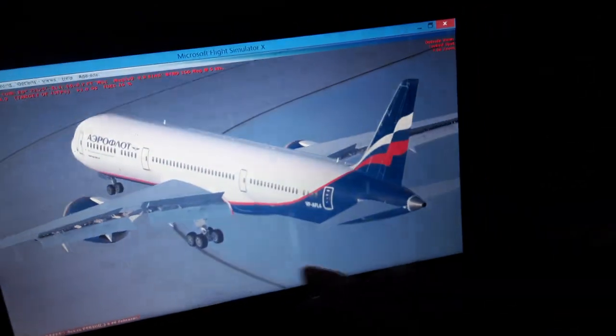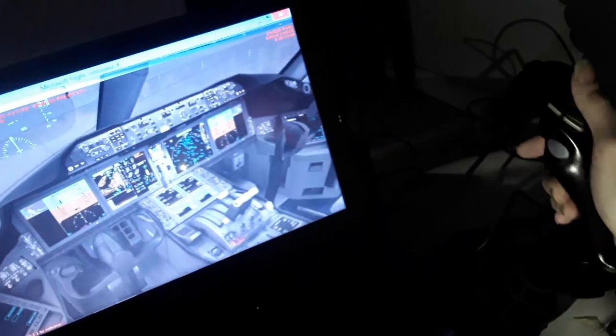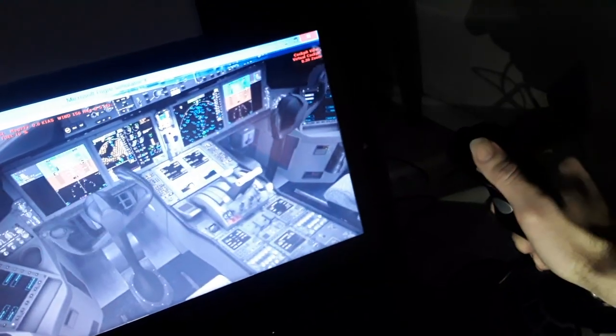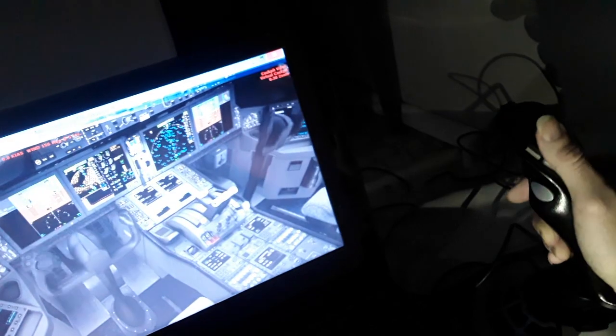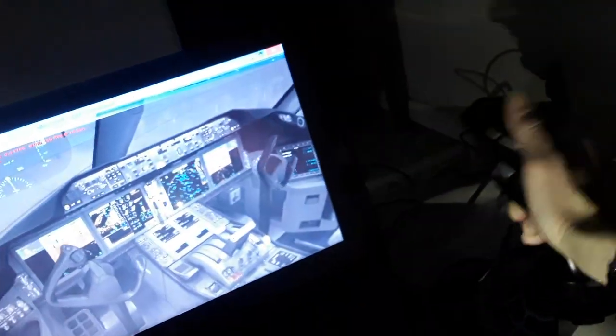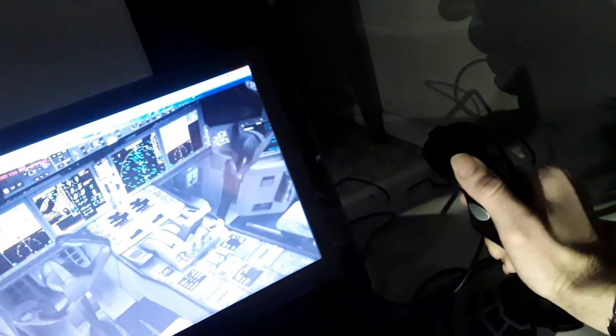Easy also. We have here the control wheel instead of the side stick, which is doing the same thing in the Boeing aircraft. Like in the Airbus, you make the roll, right or left roll, and you have all flight controls together. You have coordinated flight. For making right turns or left turns, you use both control wheel and rudder pedals.